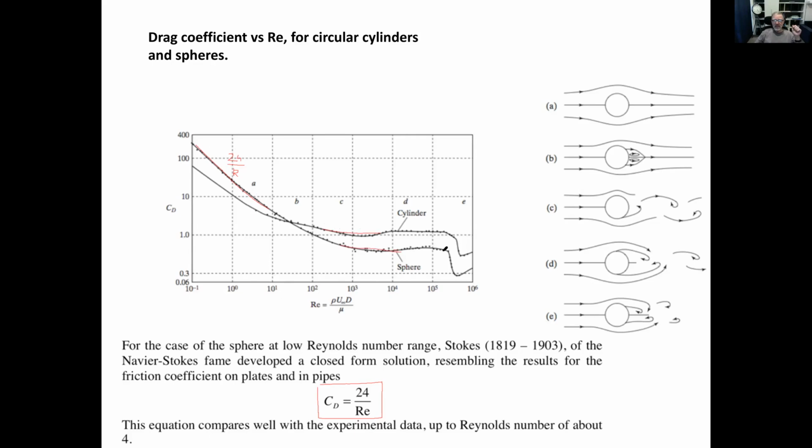And then when suddenly the flow becomes fully turbulent, like here, the separation goes from here to here. And this is called the critical Reynolds number area. And then you get actually a reduction in the drag because of that. So it's very interesting. We mentioned all the time that if your flow becomes turbulent, then the drag increases. Yes, the friction increases, definitely. But it can reduce also the area of separation, and the opposite can happen. So the drag is being reduced.